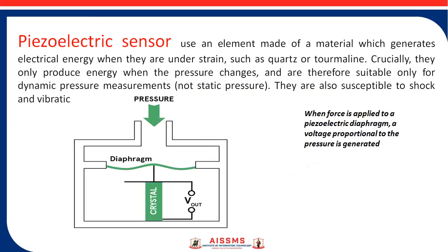Now, next is piezoelectric pressure sensor. Piezoelectricity is the ability of some materials, mostly crystals, to generate an electric potential in response to applied mechanical stress. In this sensor, the piezoelectric effect is used in certain materials such as quartz to generate rapid electrical signals and measuring the strain upon the sensing mechanism due to pressure. Common types of piezoelectric pressure sensors are charge mode type and low impedance voltage type.